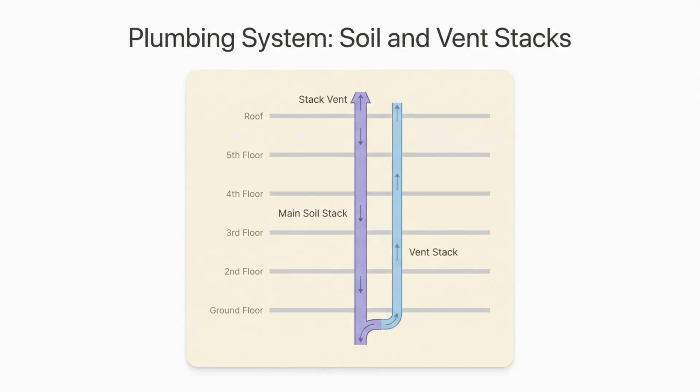Now, let's shift our focus to vertical systems, specifically vent pipes for stacks. Every single drainage stack must terminate at its upper end in a stack vent. But as buildings get taller, the rules change. If your stack drains fixtures for more than 4 stories, the volume of falling water creates massive air pressure fluctuations. To handle this, you are required to install a dedicated parallel vent stack.